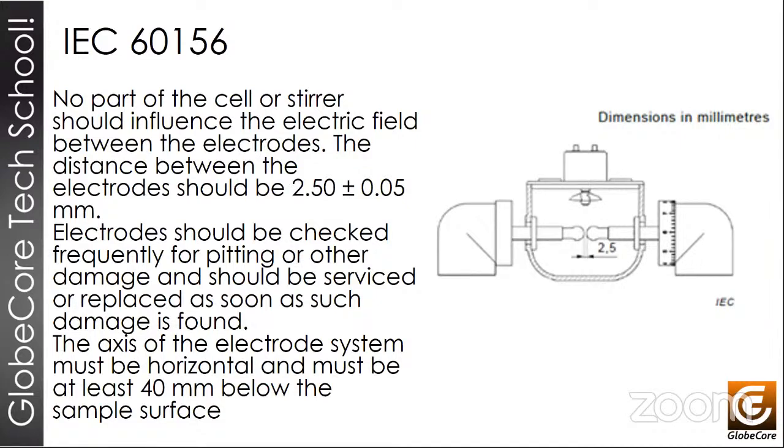Now, regarding an agitator, the use of an automatic stirring device is highly recommended at all times during the test. Such a device should be mounted on the test cell to maximize the homogenization of the liquid sample. It must be designed so that it can be easily cleaned. Stirring must be performed by a two-blade or another appropriate agitator or impeller with an effective diameter of 25 to 35 millimeters, with actual depth of 5 to 10 millimeters, rotating at about 200 to 300 RPM. The agitator vanes must not produce air bubbles in the oil, so it must be completely submerged in the sample.